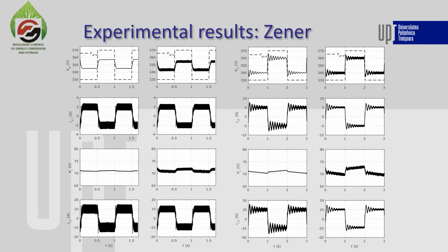When operating in constant voltage mode at a larger current, at plus minus 5 amps, we see that some dampened oscillations are shown for the currents of the converter, which is expected because in this range the virtual resistor is considered to be zero. But in this case, the bus voltage is still limited to 340 or 360 volts. The oscillations are the main reasons for which the next method was developed, even though it was expected because of the harsh characteristic of the Zener diode.